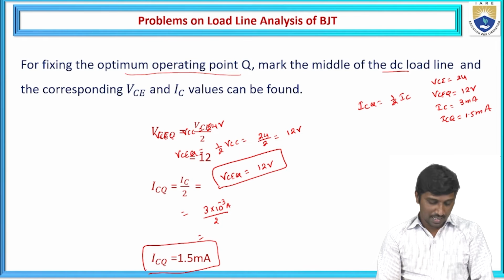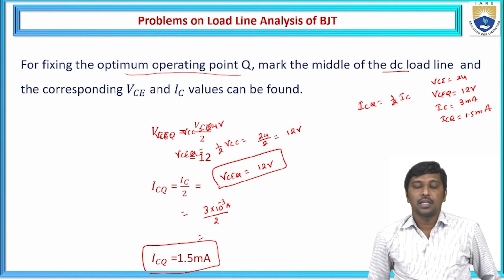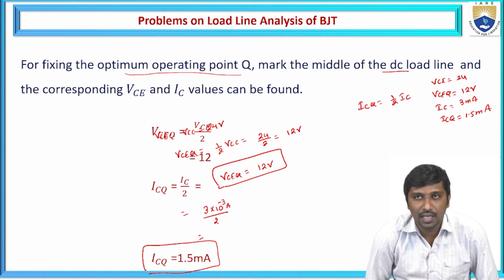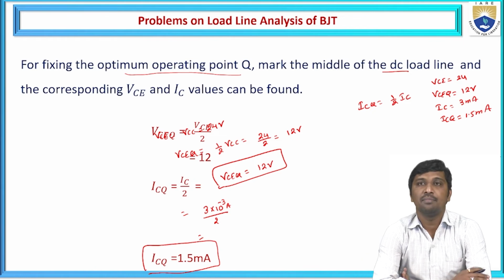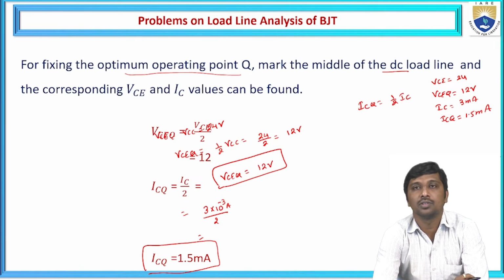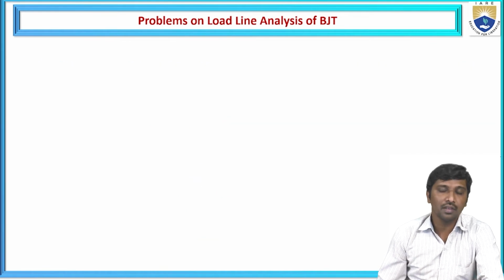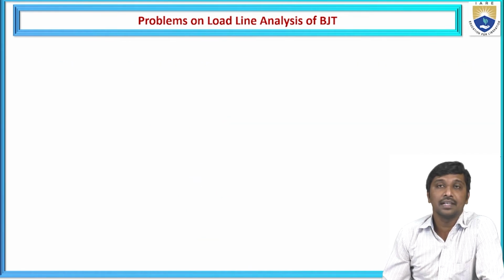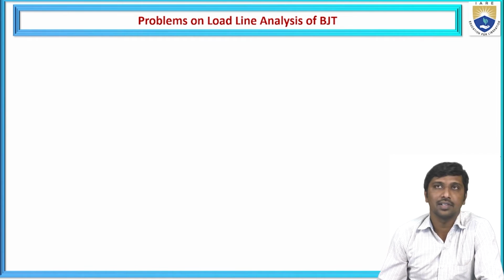Now we need to calculate further. If you observe the amplifier circuit, the amplifier circuit is the superimposing of the AC signal and DC signal. So we need to find out the AC load line analysis concept also. To determine this AC load line, based on the theoretical concept, the AC load line also passes through the Q point, as does the DC load line.